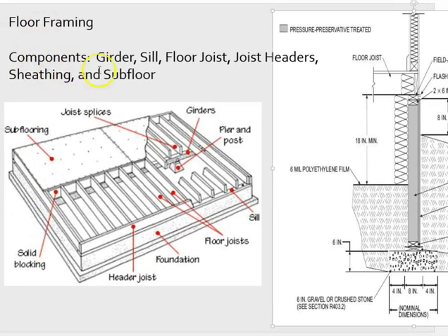There we are. So the components again. We have our foundation, girder running below. So here's a pier. That vocabulary came up when we were talking about foundations. And so this is a pier in a crawl space setting, a small concrete column. That's what you would call a pier. The girder's running across, and the joists in this situation are sitting on top of the girder.